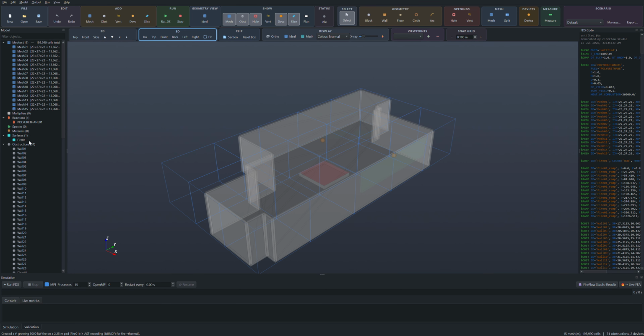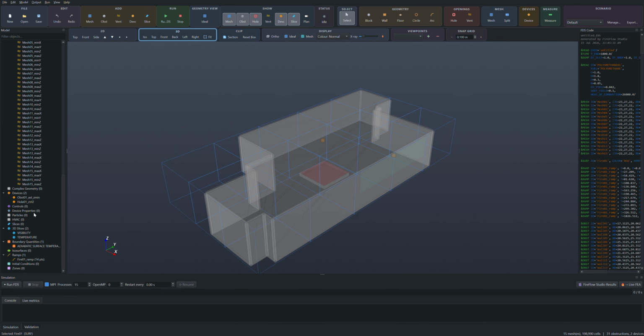And to show you what that does, it automatically creates your reaction. It automatically creates your fire obstruction. It automatically sets the surface which you selected as a burner surface. It creates the burner surface entry, and it also creates the fire ramp.